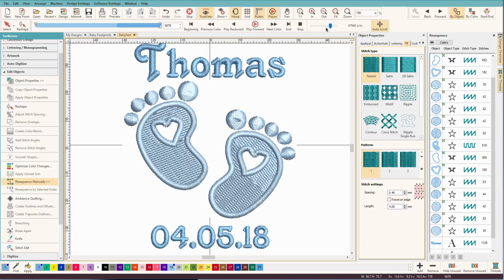Now once you're ready to save it out, let's do a save. I just did Control S, and that saved it as an EMB file. You always want to save your EMB files. That's your master file. Even if your machine, well, actually no machine is going to store an EMB file. Your machine has a specific format. Maybe it's PES or DST or some other format.